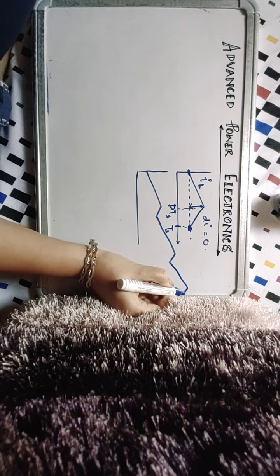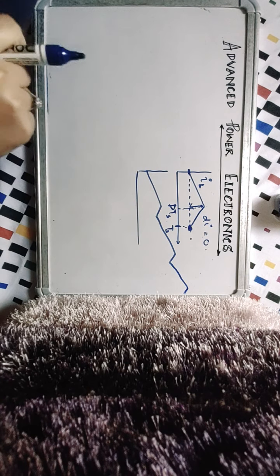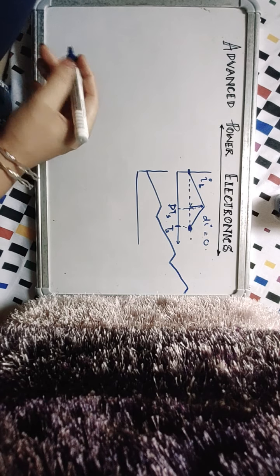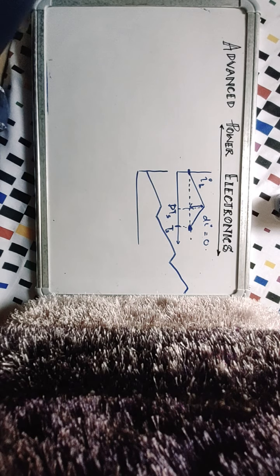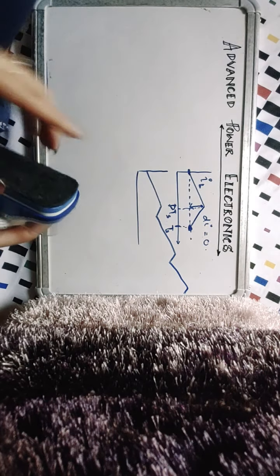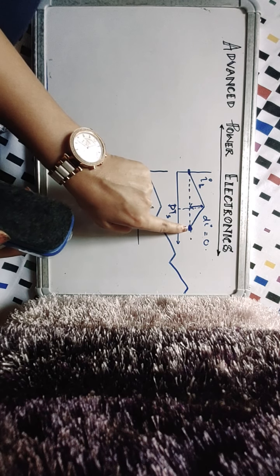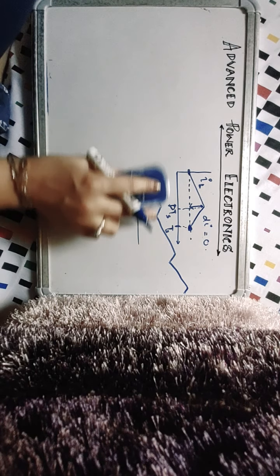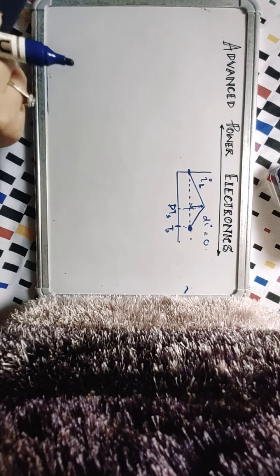So basically that is an inductor going into saturation, or operating on a DC supply. But here you have an inductor operating on a switched DC supply, where you are ensuring that the inductor does not saturate by bringing it back to its initial value of current, and you're ensuring that it does not just go on storing energy, but it also releases that energy effectively, so that it has no net consumption of energy.